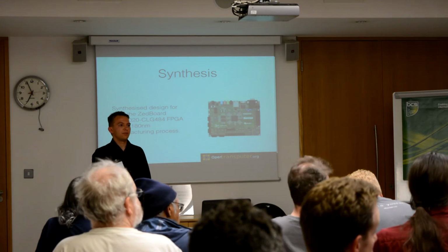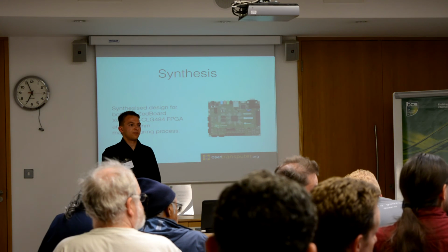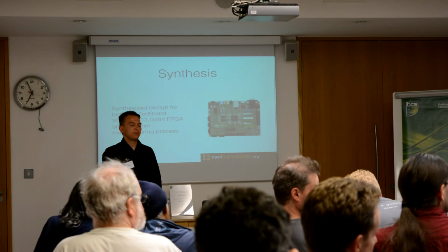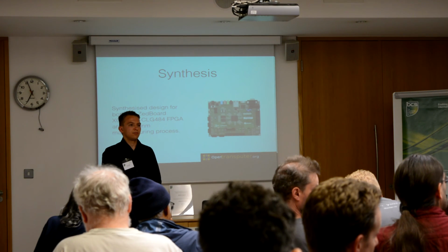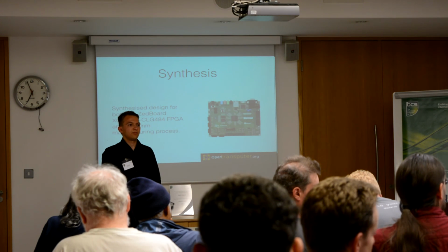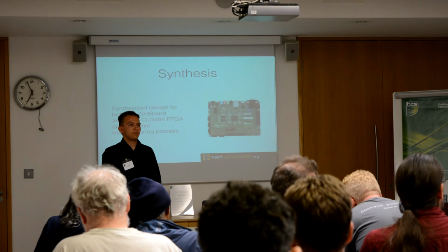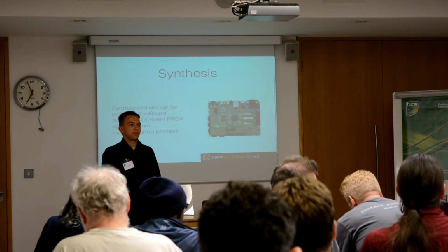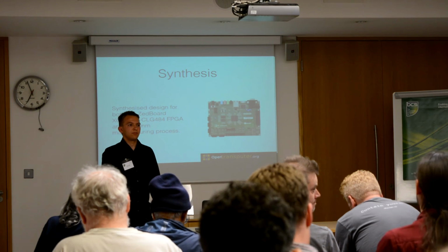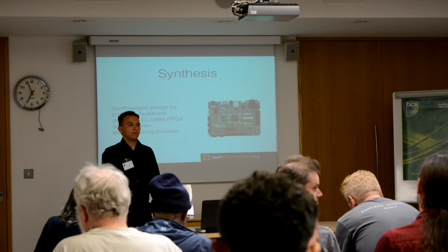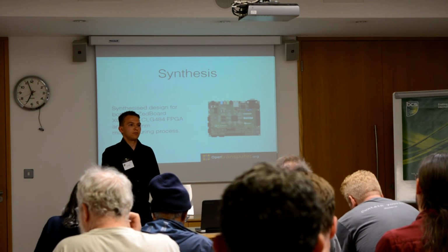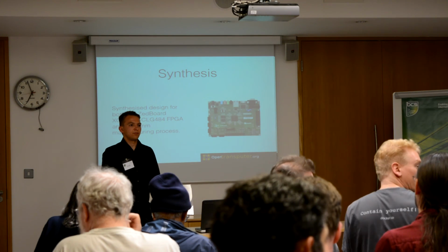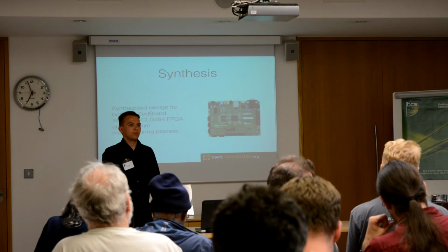There were actually some pretty fast Transputer implementations done in the 1990s. But it is a slightly tricky one to do because of the register stack, which essentially makes every instruction to some extent dependent on the previous one. And that's one of the disadvantages of the stack architecture. On the other hand, it would be quite interesting to know more about the performance here because it is a very simple processor. Synthesized to anything like a state-of-the-art process, it would be limited by the memory speed almost certainly. So there's an experiment for somebody to do.